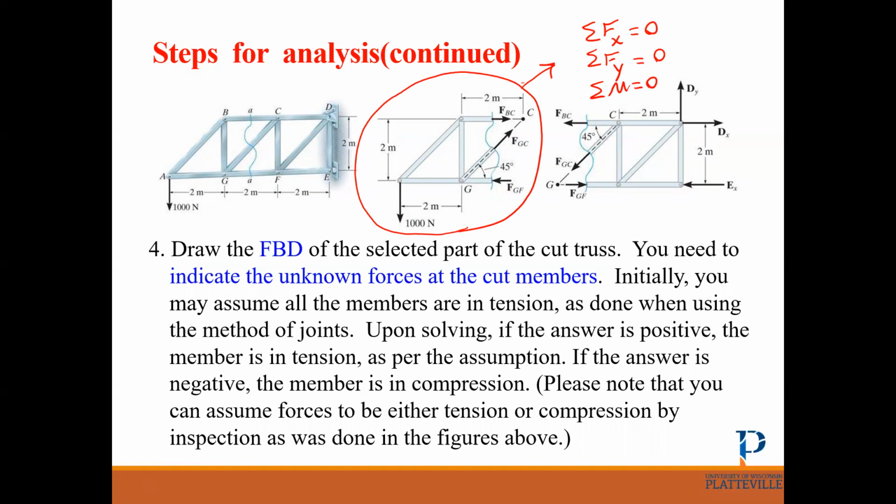Sum of Fx and Fy equals 0 is easy, but usually the tricky part is sum of moments equals 0. Which point is a good point to take the moment about, so that you can get rid of a lot of internal or external loads? So this equation is the most important one.